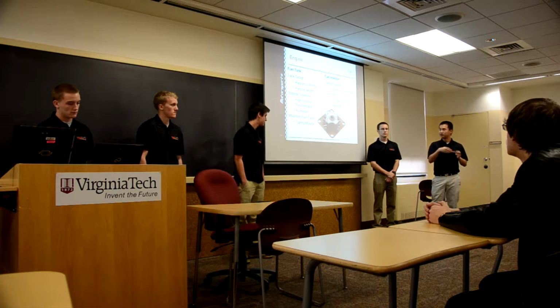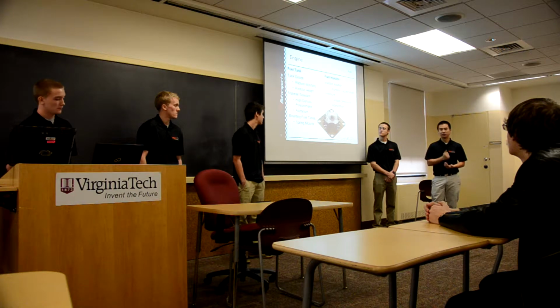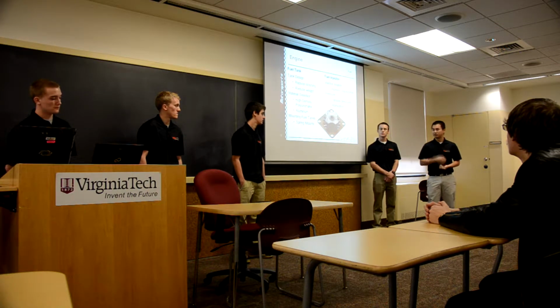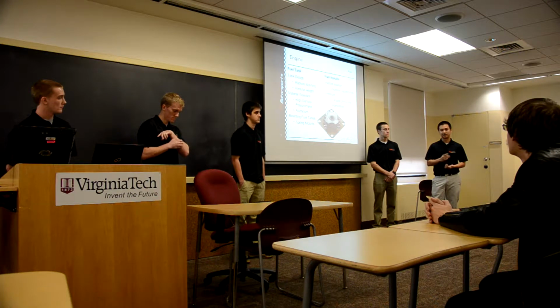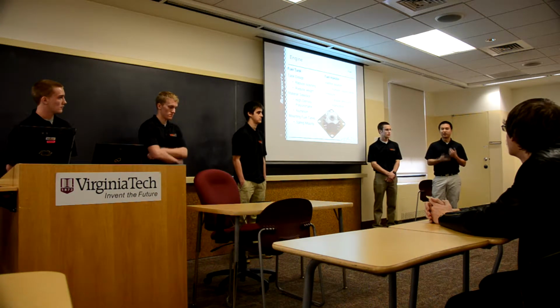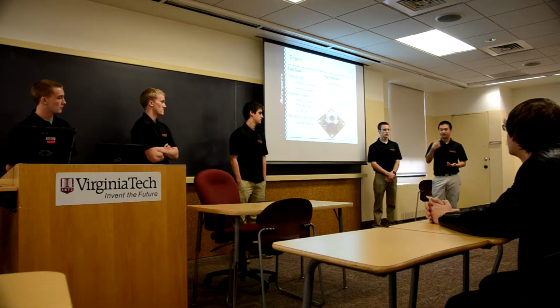Another thing I want to talk about is how I'm going to reduce the weight. Right now I'm looking at two materials, high density polyurethane and aluminum. Some of the benefits of high density polyurethane are that it is lighter weight and more chemical resistant. But some of the cons are that we don't have a lot of experience manufacturing it, and the cost of manufacturing is a lot higher, because some of the methods used to manufacture it are blow molding and plastic welding, which I'm sure we're not capable of in shop.